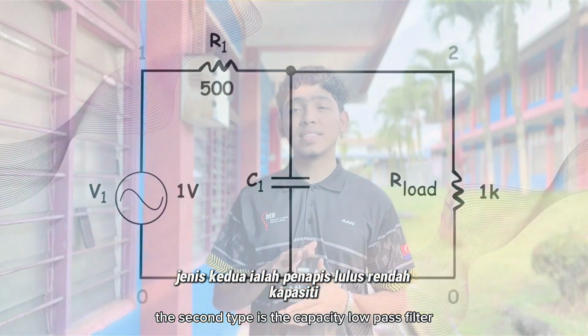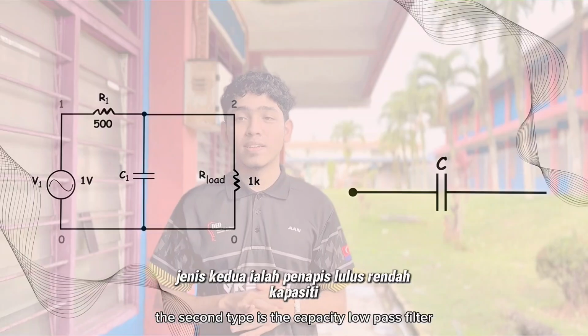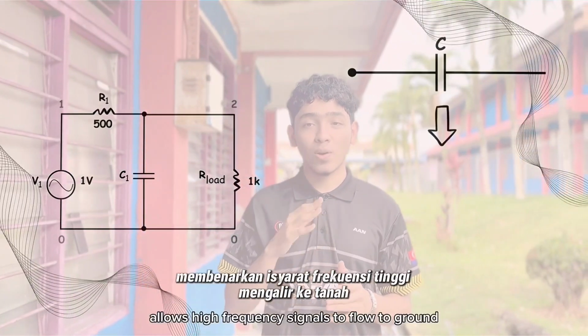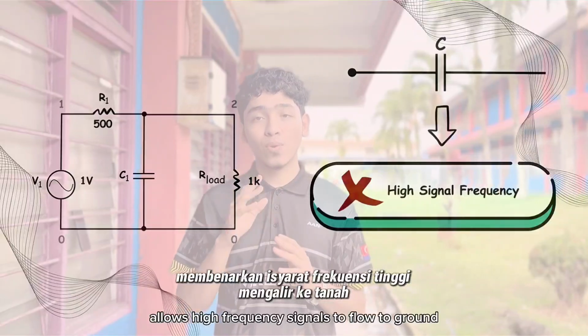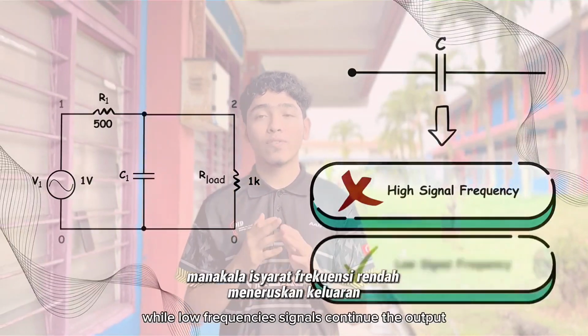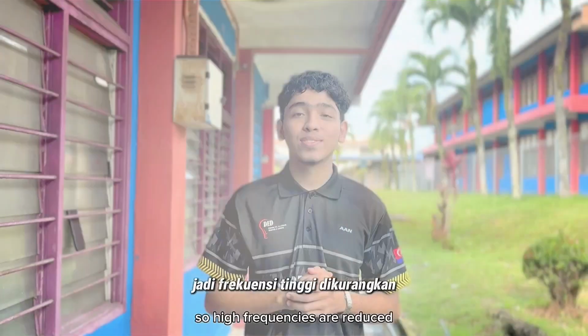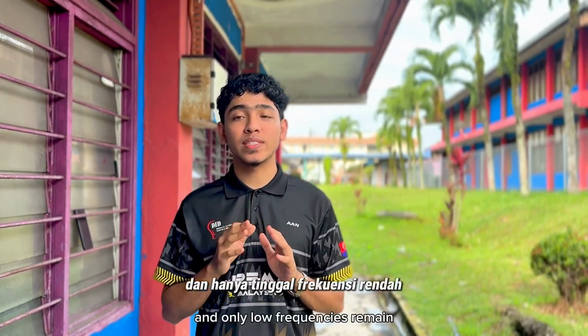The second type is the capacitive low pass filter. This filter uses a capacitor. The capacitor allows high frequency signals to flow to ground, while low frequency signals continue to the output. So high frequencies are reduced and only low frequencies remain.